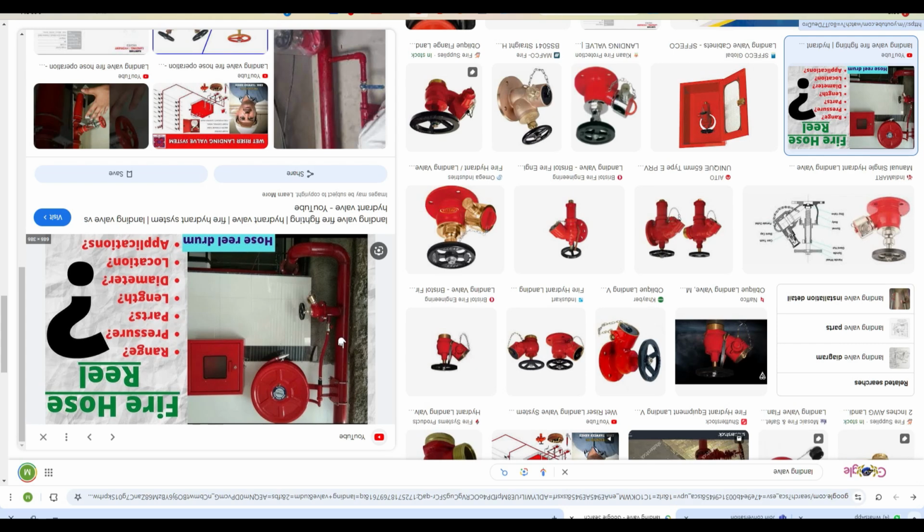So once the water is ready here, in case of fire, anyone can just open this valve and start throwing the water using this reel, and this reel can reach up to 30 meters. So note this down. The length of the hose reel is 30 meters, and the size of the hose reel pipe is 25 mm. Clear? And the flow it will deliver in operation is 50 GPM, 50 gallons per minute of water. Standard, just remember these things.